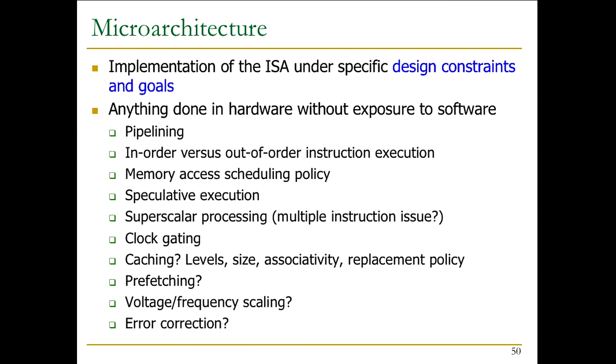Now, you can do multiple instructions in parallel in a VLIW machine, and that's part of your ISA. Your ISA is inherently parallel, right? It's sequential across those instructions, but each very long instruction word consists of multiple operations at the same time. And you go to the next instruction, and then the next instruction, but each instruction can do, let's say, 28 operations, right? 28 actually was the number of operations that you could do in the Multiflow machine by Bob Colwell. So Bob Colwell actually designed a lot of the VLIW machines at that time.